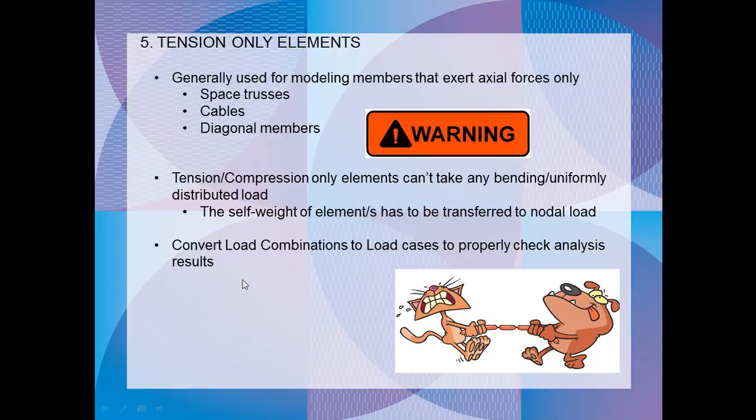Before continuing, we also have to convert the load combinations to load cases to properly check analysis results. This is due to the fact that when we do a load combination, they are being additive, and therefore the results are going to be wrong. So we have to convert the load combinations to a load case so that they can act properly on the model. Let me show you how that's done also.